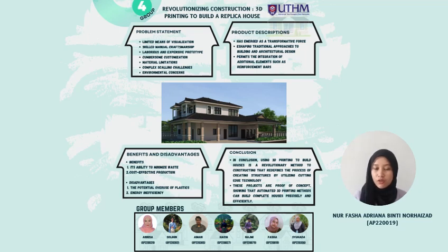Construction-grade materials like concrete or mortar are chosen for their extrusion and curing properties. A 3D construction printer mounted on a robotic arm follows a precise toolpath to deposit material layer by layer through extrusion or binder jetting. Customizable features include structural reinforcement with elements like reinforcement bars and the ability to embed conduits and voids for utilities during printing. Post-processing involves finishing touches like painting and insulation.